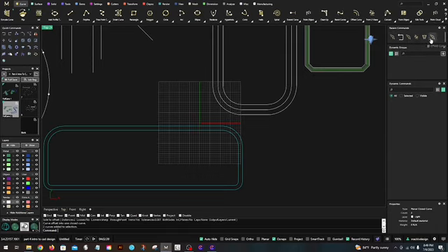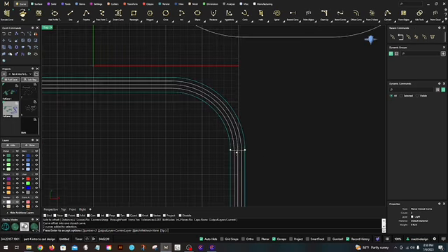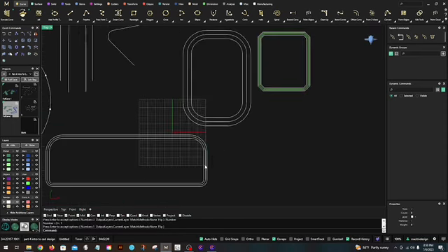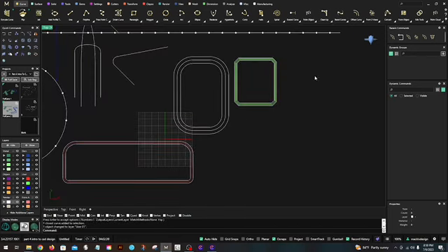and it will have in order all the different commands that you did. So the latest one is here. So I'm going to select tween curves, and look at that. It defaulted to the very last input. The last input I did was 3 curves. So if I want 1 or 2, I'm going to have to change that. So I'm going to select 1, press enter to accept, and there you go. That is my tween curve right there, the red one. All right.